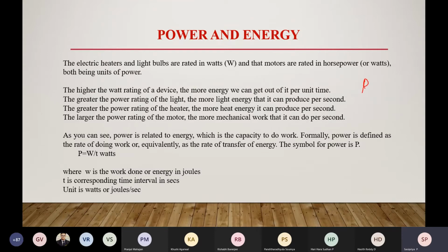Most of the loads available in our households are resistive loads or inductive loads. Whichever load gives heat energy as an output is resistive. A bulb will give heat energy, your iron box, your bread toaster, and so on. All these are different examples of resistive loads. Wherever you have a magnetic coil, that is wherever you have a motor, your fan, your washing machine motor, refrigerator motor, all these are examples of inductive loads. Whereas a capacitive load is normally very minimally used.